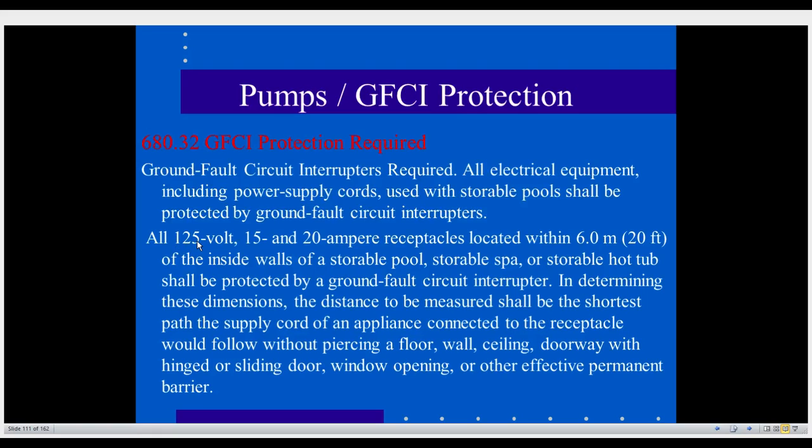If it was 120, we'd be talking about the actual branch circuit itself, but here we're talking about a device, and it says all 125 volt, which is actually a NEMA rating, 15 and 20 ampere receptacles located within 20 feet of the inside wall of a storable pool, storable spa, or storable hot tub shall be protected by a ground fault circuit interrupter.